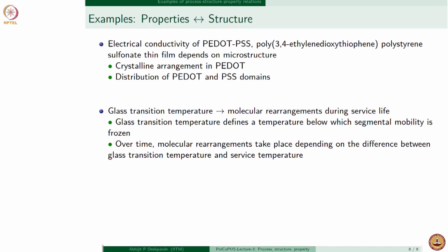And as we will learn during this course, it is possible to get a conducting polymer, the example I have given here is called PEDOT:PSS. You can search for it and you can find a lot of information related to PEDOT:PSS. In fact, it's available as ink. So I can use an inkjet printer to actually print electronic devices using PEDOT:PSS. Very interesting, isn't it? So the repeating unit in this case is ethylene dioxythiophene.